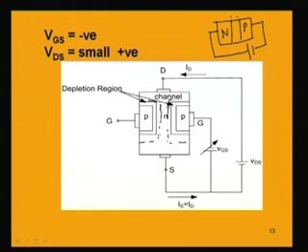So now the width of the channel is narrower, which means the drain current will be going on decreasing, because the drain current is dependent upon the charge carriers present in the channel. Now the channel is narrowing down, means what? Lesser charge carriers will be available to flow. So the current between drain and source will be reducing.